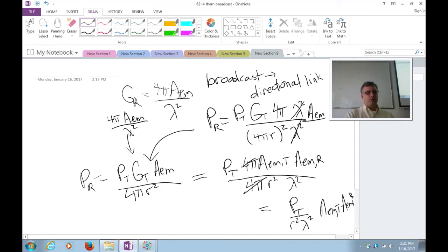So remember, electromagnetic aperture is effectively proportional to the physical aperture of my antenna. But it means I have to point it. I only get that maximum electromagnetic aperture if I point the physical aperture towards the radiation, gather all the energy, and it's being excited by a wave in such a way that you get constructive interference across that aperture at the terminals of the antenna. Like a dish antenna. Think of a parabolic dish reflector.